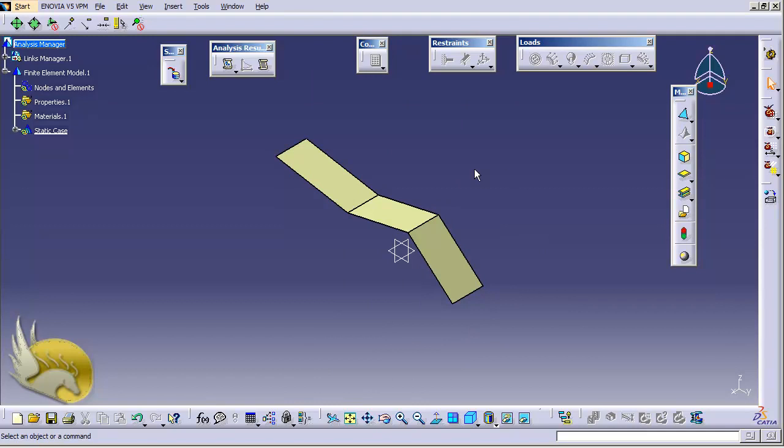And now I want to add some mesh into this face that I have created. And you can see that this is not meshed by default. You cannot see that green sign inside this part. So I go to Model Manager and select different types of meshing that's available here. You can see that I can have 3-dimensional meshes, I can have 2-dimensional meshes, and I can have 1-dimensional.